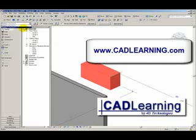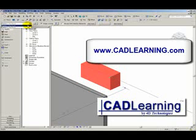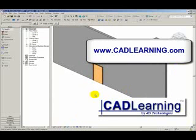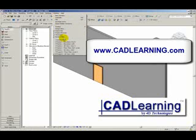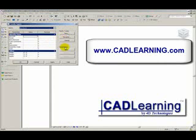And the 2 types are available, and I can select the 2 types and change my component from one to the other. This is exactly the same process as when you change the door from one type to another. So in your family file, in your family editor, you will create family types. Once you've created more than one, you can rename any type within a family, and you can delete family types.